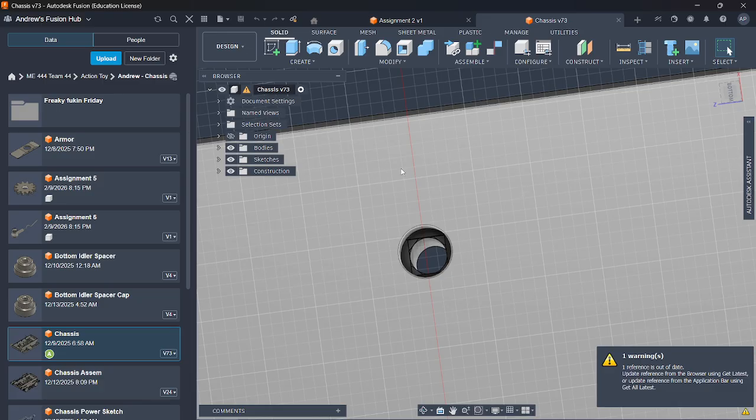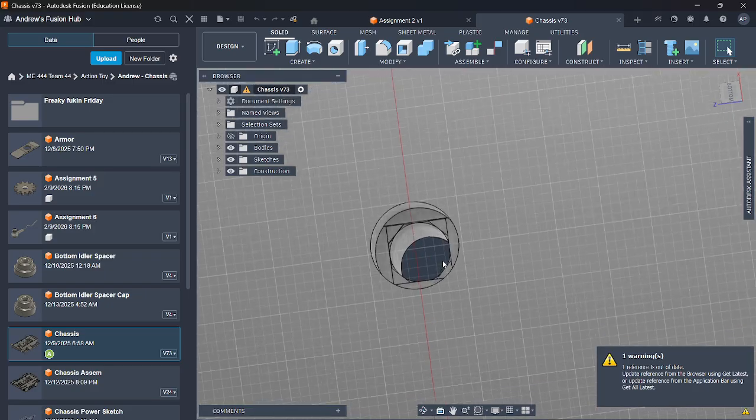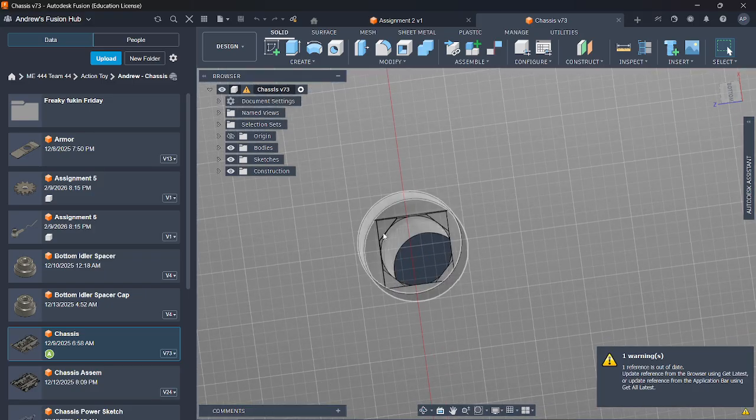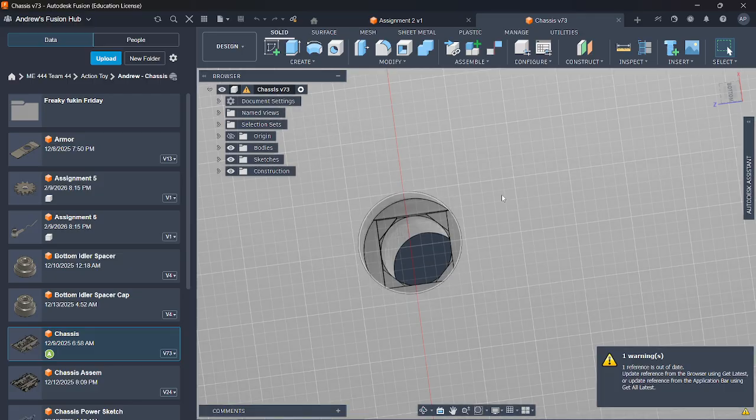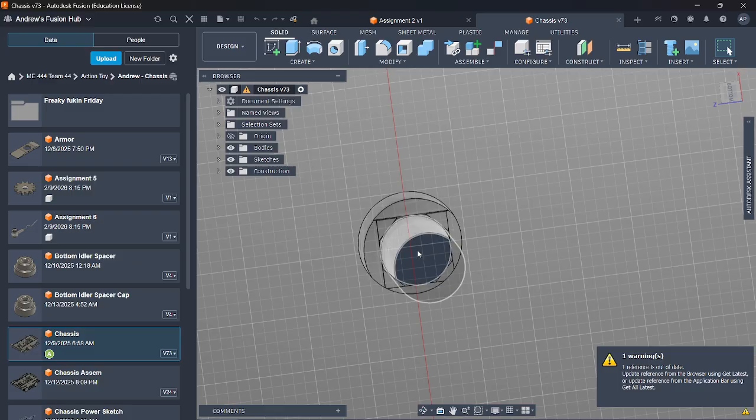The slicer prints the perimeters first, and then the other stuff. So for a hole, it will print the inside of the circle, and then fill in the stuff around it. But if you try to print something in the center here, it's going to print in midair, and it's just going to droop, right? And it's going to be super sad unless you have supports.